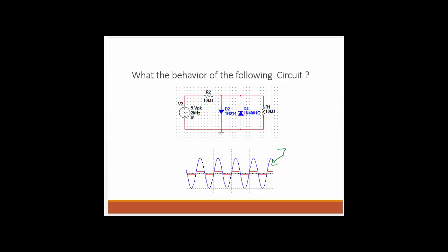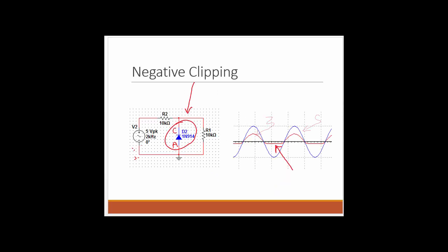As you can see, the input signal is clipped on both half cycles. It clipped on the positive half cycle as well as it clipped on the negative half cycle. So that's what a diode limiter does. But if you observe on all of these circuits, the clipping voltage is always 0.7 volts because I have only a single diode placed, or in this case multiple diodes placed across the load resistor. But I cannot change that 0.7 volts if I want to use only one single diode, because if I use one diode, as long as it is forward biased, I'm going to only get that 0.7 volts.